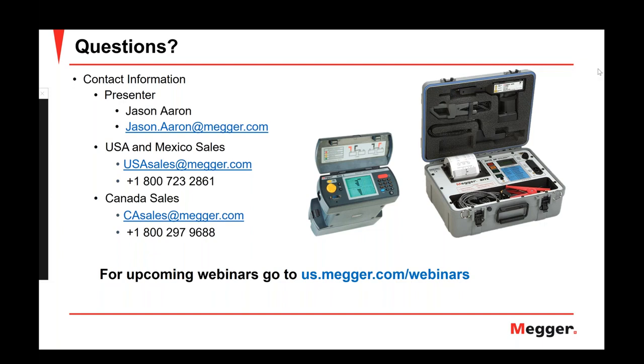One typical example is NiCad batteries. With NiCad batteries, you can do the measurement and you get a result. Under certain conditions, the impedance on a NiCad battery might change, and that is a clear indication that the battery is in a failure mode, and the capacity is probably already gone, or very reduced. However, it will not always change when the battery deteriorates.